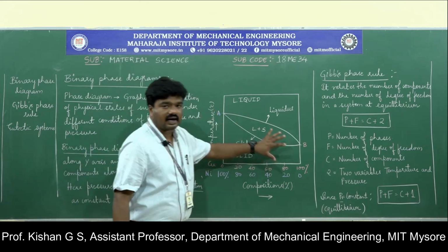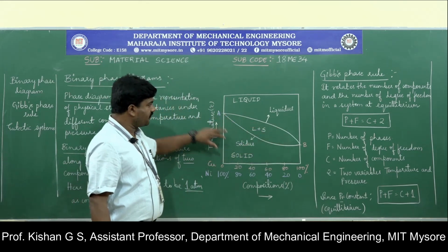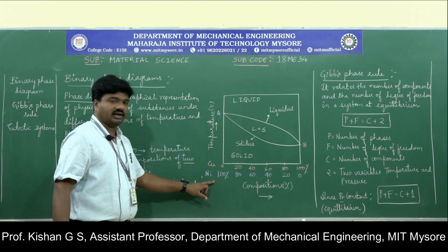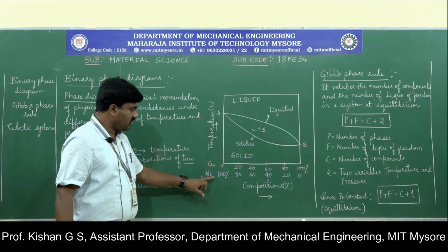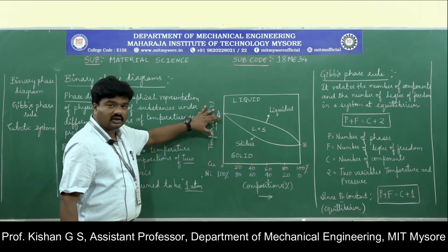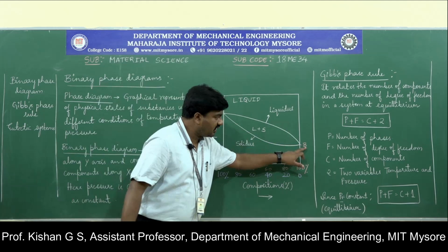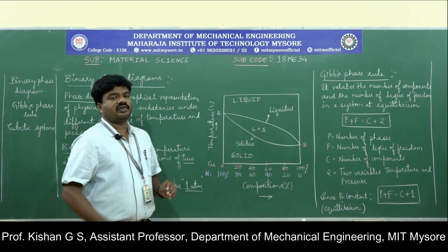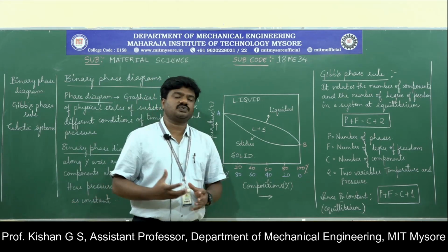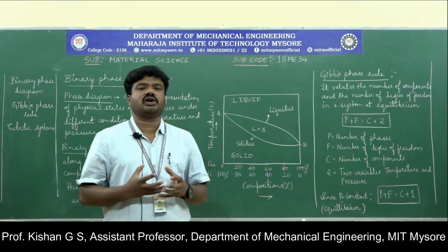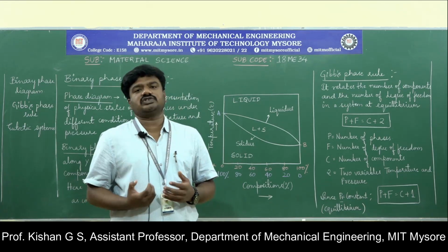In this particular diagram, you can observe A is the melting temperature of nickel. I have quoted A along the same color chalk for reference. So A is the melting temperature of nickel, whereas B is the melting temperature of copper. When we have the combination of two materials, we heat the material so that the materials merge with one another in the liquid state and then we solidify.